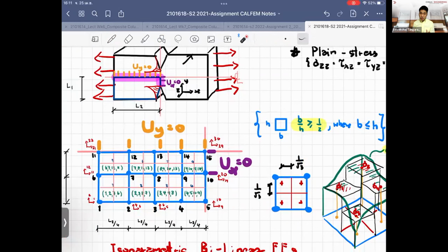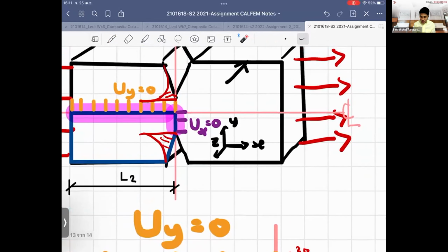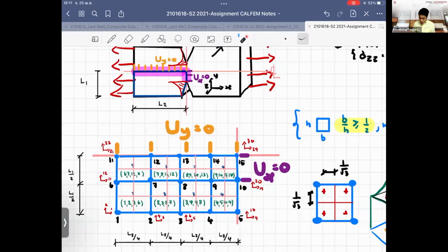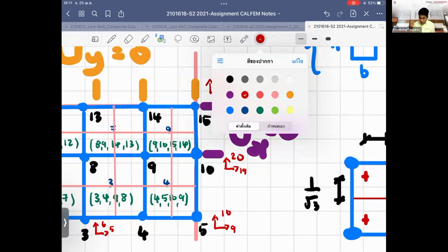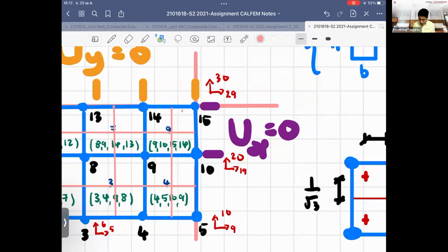Sometimes I will show you the nice element later, right? But in most cases, when we find the problem is this notch, the crack tip is a problem. So you need more elements around the crack tip to approximate the sudden change or the high variation of the stresses, so that we can capture the high order variation of the stress. To satisfy this, I need to discretize this area more. So what we do, definitely, is divide more elements in these areas.